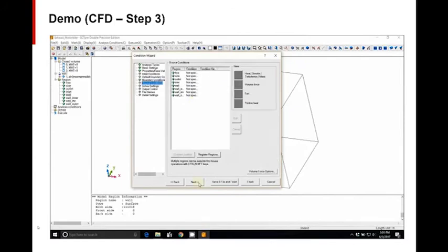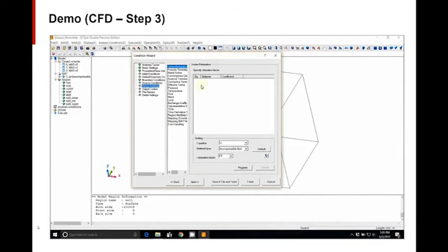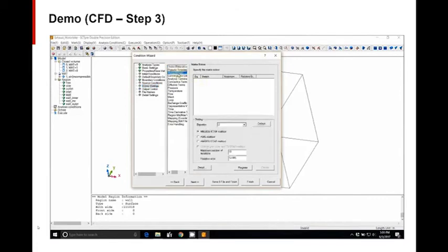So once we're done with this, we can save this as an analysis condition file, called an S file. And the FLD file is the field data for the CFD results. In this case, we're running the simulation to get the data for acoustics, so I just choose the option not to write it. And we give a file name, and that completes the setup for CFD.